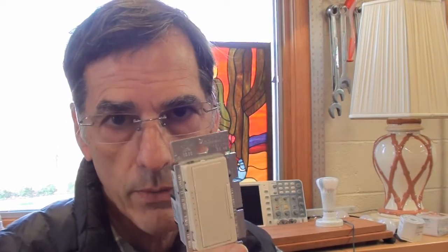So in general, this is a good choice for a single location if you need those features for slow up, slow down dimming, or push it, the light stays on while you leave the room and it dims down. Those are neat features, but if you don't really need those features, or you have a 3 or 4-way switch, I would avoid the Lutron.